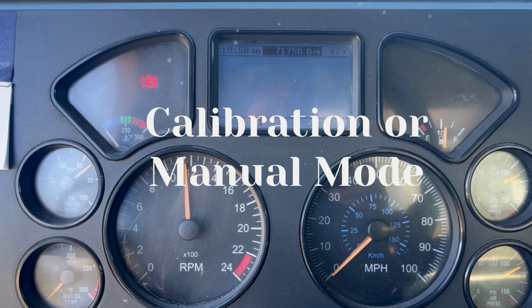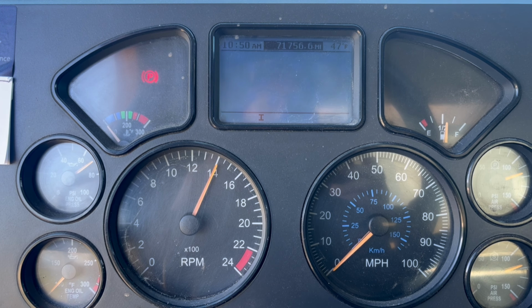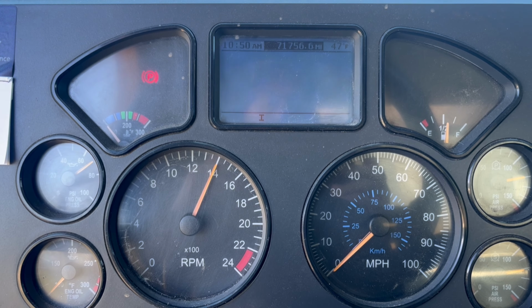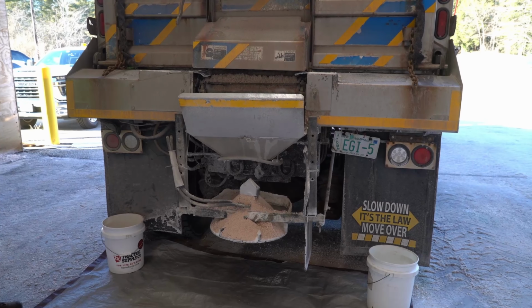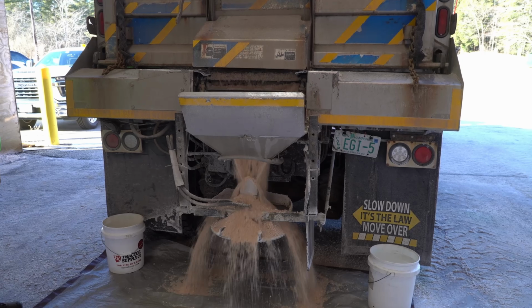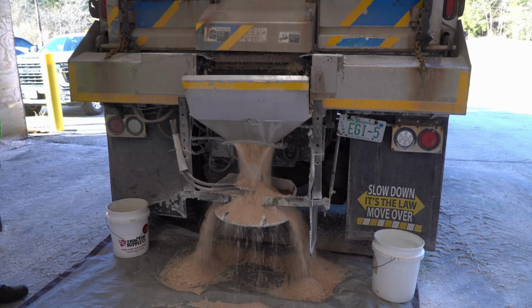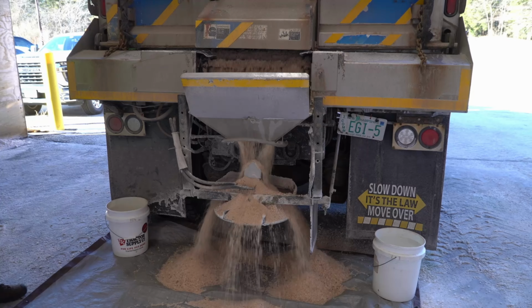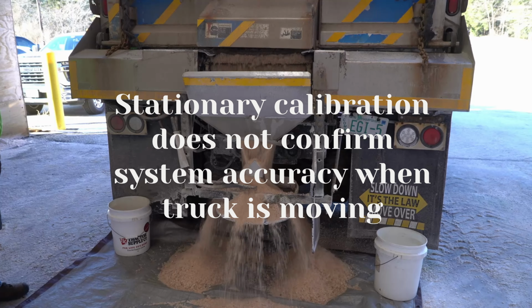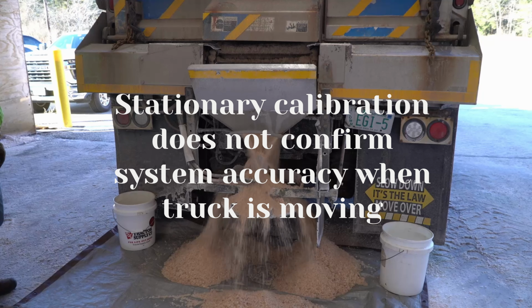This will require the system to be placed in a calibration mode or manual mode to bypass the ground speed controls since the vehicle is stationary. The vehicle's RPMs should be brought to between 1,300 and 2,000, which is dependent on normal operating RPMs for 20 mile per hour travel. We then run three 30-second time captures and use the average of those three, convert to pounds per minute, and then compare actual output to expected output. Through this, we can determine if, within reason, the spreader is physically producing the required discharge rate under stationary conditions. However, this does not confirm how accurately the system responds while the truck is moving and speed is changing.